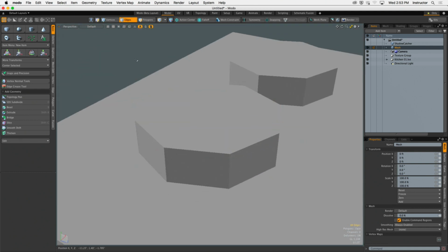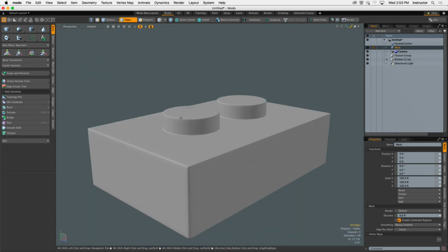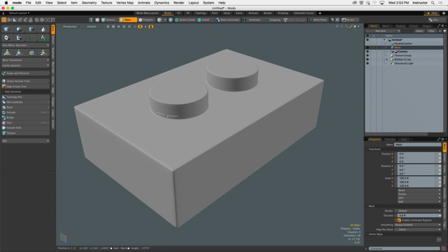So use sub-Ds. They really are powerful. This is going to give you the best result. I used to say a long time ago that this was the way of the future, subdivision surface modeling. It's no longer the way of the future. This is how everyone does it. So start practicing it, okay? Hold yourself to that standard, and you're going to get there.